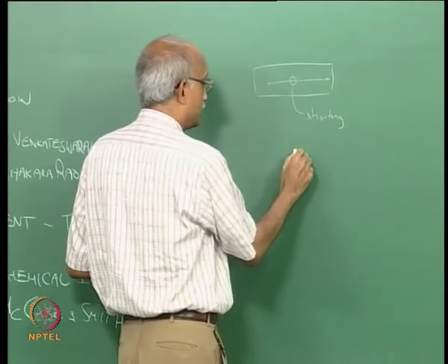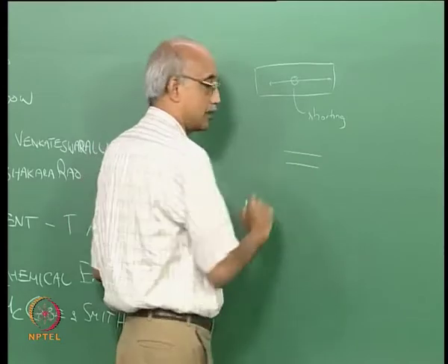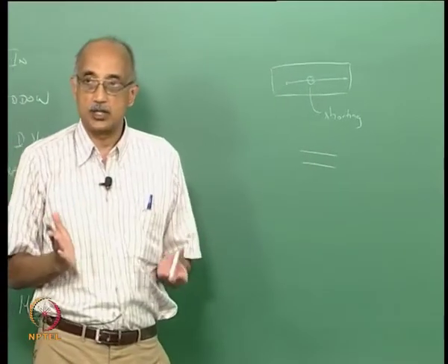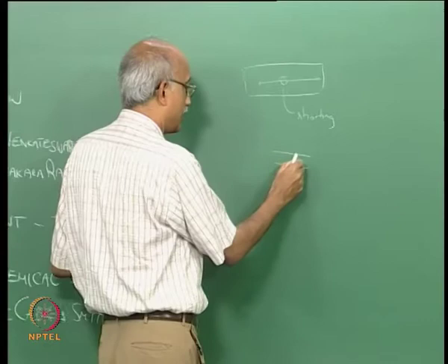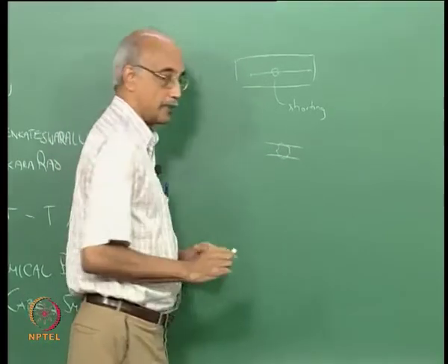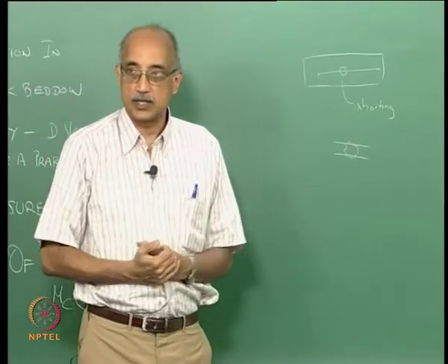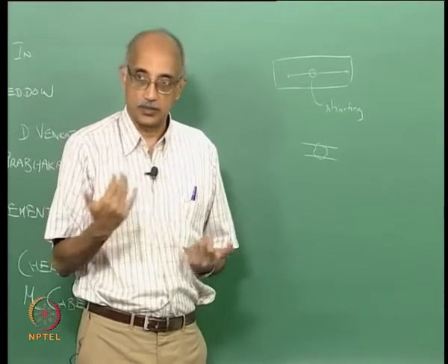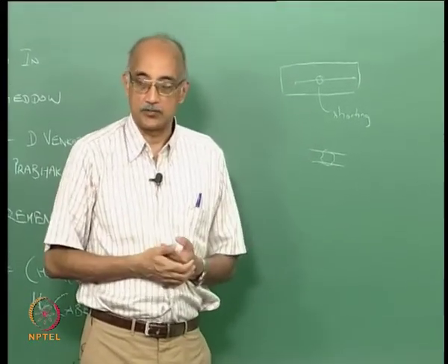Or alternatively, if you have two parallel paths which are designed to be non-conducting and you get a conducting particle deposit so that it bridges those paths, then you get a conductive path which is going to interfere again with the functionality of the device.